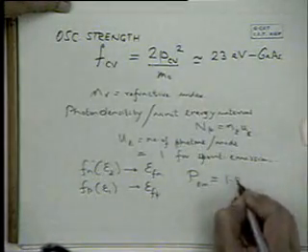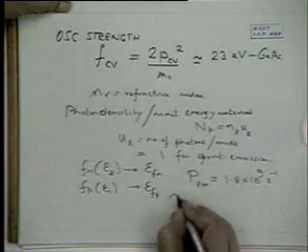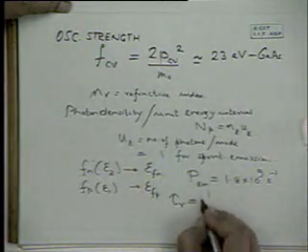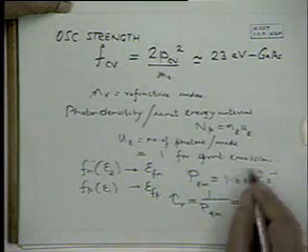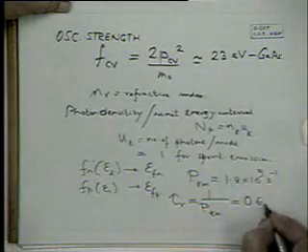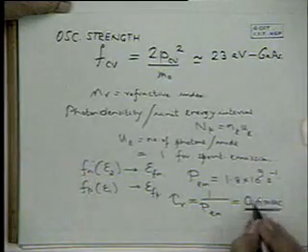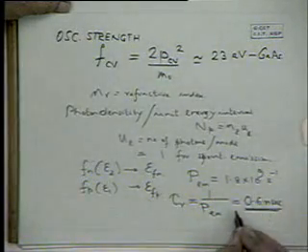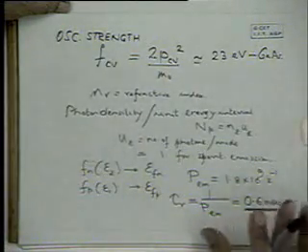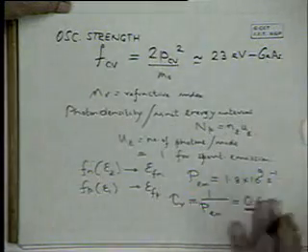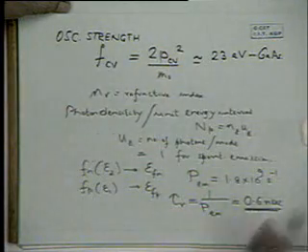The emission probability turns out to be 1.8 into 10 to the power 9 per second. And so the inverse of the emission probability is the recombination lifetime, the direct recombination lifetime, which is 1 by that, which turns out to be 0.6 nanoseconds. This is in good material, which is not very heavily doped, does not have a lot of defects. There are no non-radiative recombination centers. So the lifetime is of the order of about 0.9 nanoseconds.